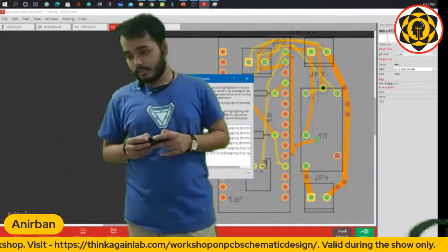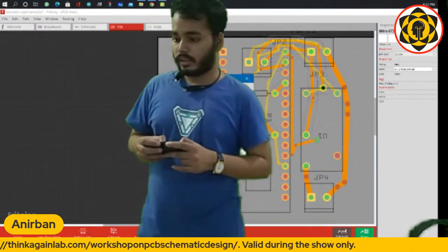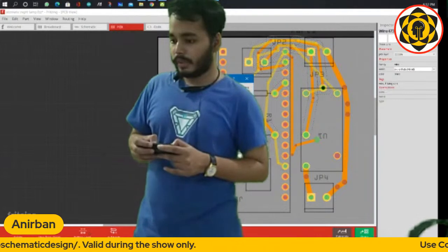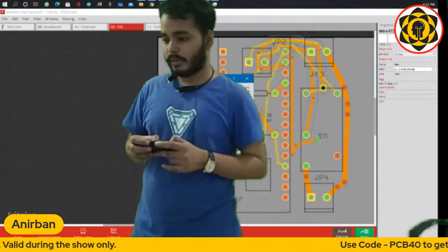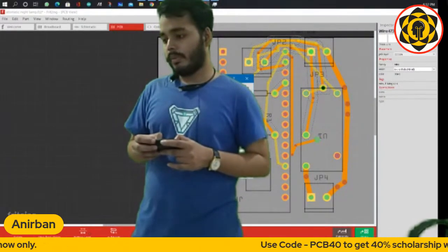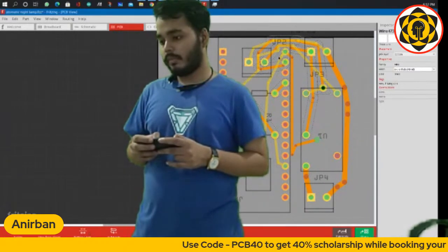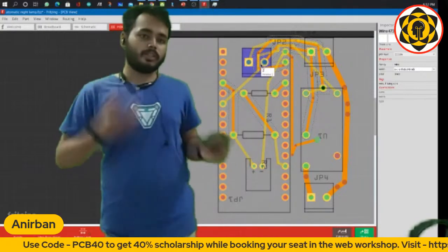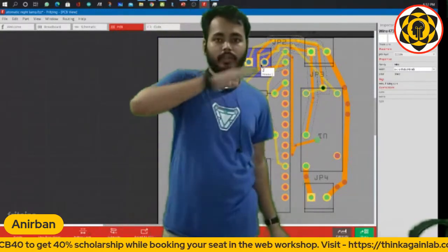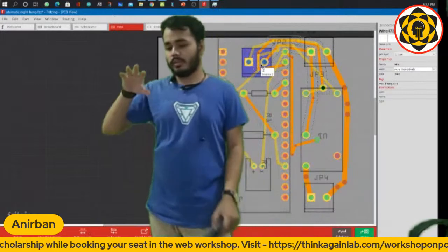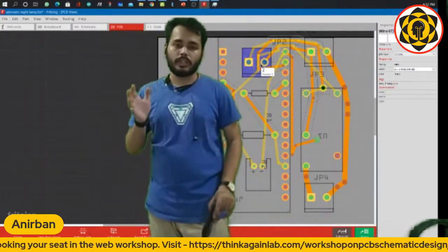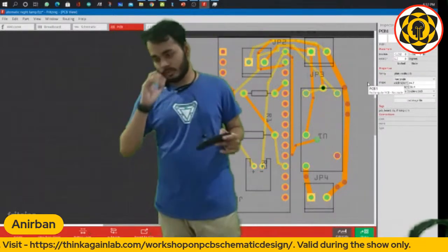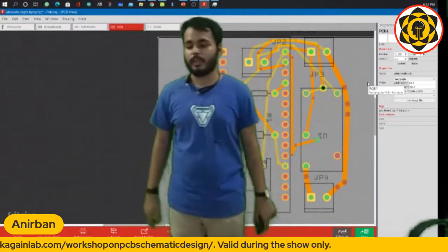Yeah. See, if you look at the errors carefully, wire 600 is overlapping bottom layer, wire 660 is overlapping bottom layer, wire 671 is overlapping bottom layer, top layer, top layer. So this is basically detecting every single overlap in the top and the bottom layer. That does not really matter because the top and the bottom layer are divided by the substrate. So these are just warnings, not actual errors. So we solved our errors basically. So this is now ready for fabrication.